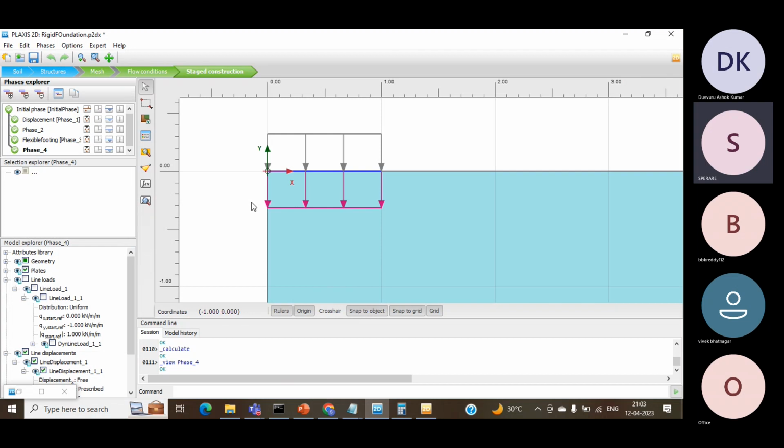So that's where it has proved that we were reaching that 188 kilonewton per meter square of load. And 188 times pi times 1 meter squared that we are applying gives a total of about 590 kilonewtons of load.